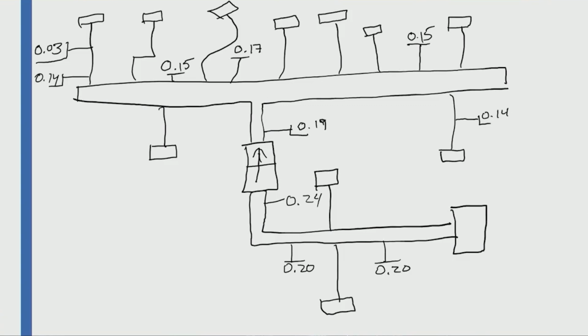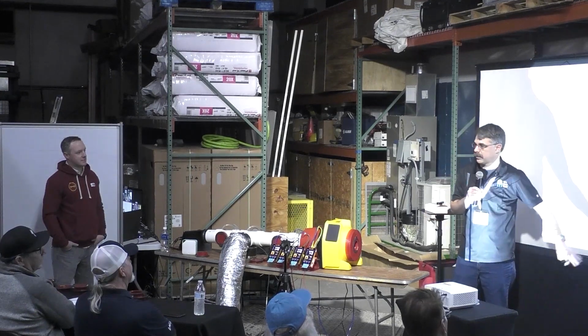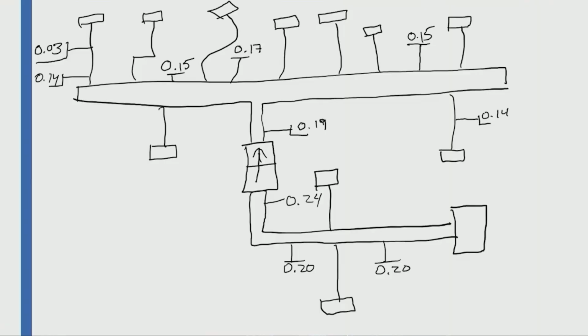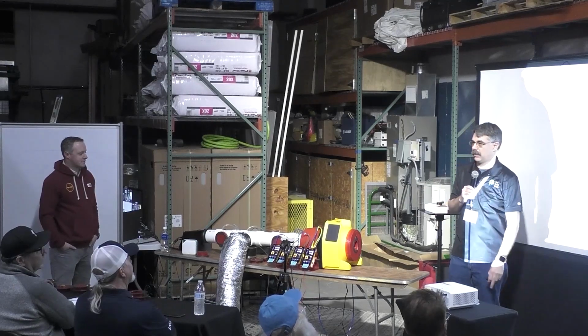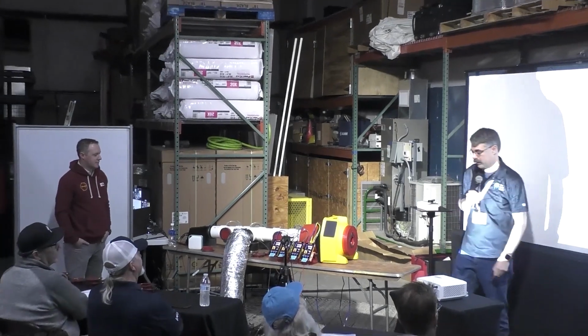I'm looking at my return. You see equal pressure across there. That may be a sign, if there's no duct size change, that I might not be pulling much air in from these two. I might just be pulling all my air straight through here.